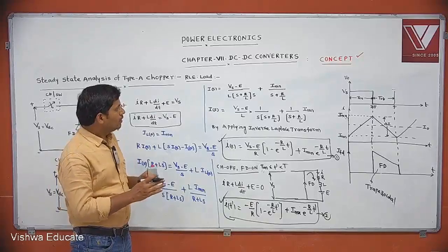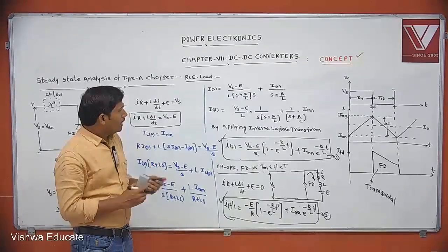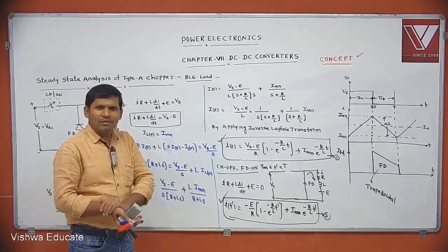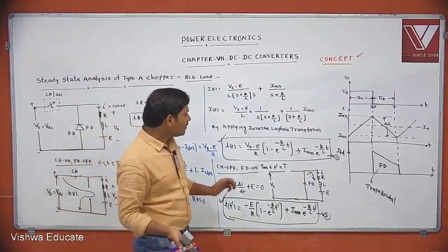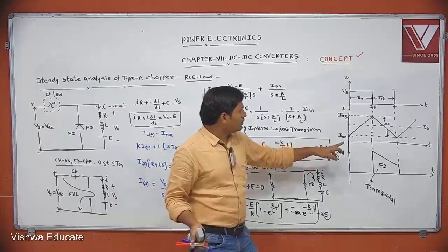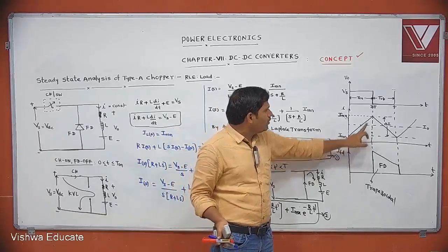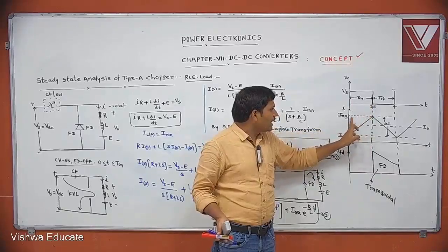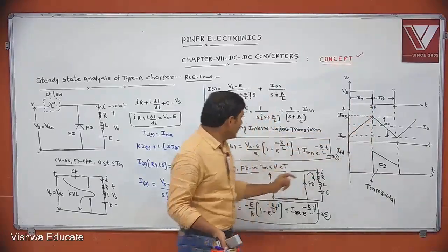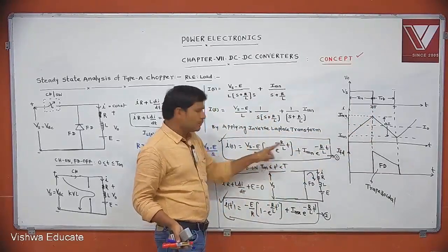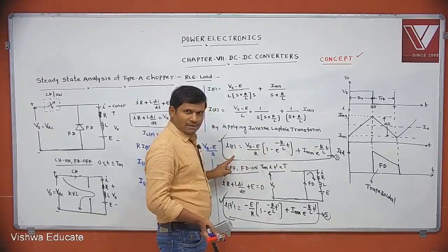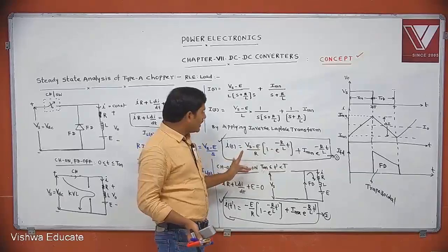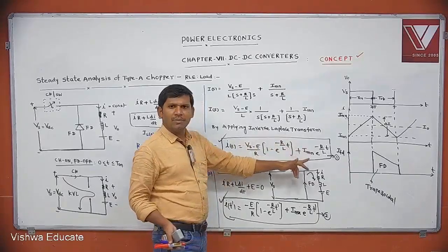Now you see, listen please. We want to solve these equations to get the minimum and maximum current. You tell me, whenever t reaches t on, the current reaches the maxima. That means at t equal to t on, I of t becomes I max. You substitute I max here, replace t by t on. Then you can get one expression for I maxima in terms of I minima.